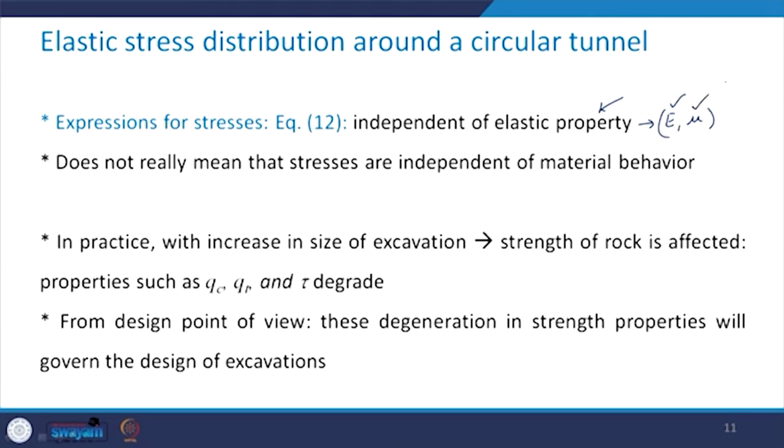So, this does not really mean that stresses are independent of the material behavior. What happens in practice is that with increase in the size of the excavation, the strength of the rock is influenced, and the strength properties such as UCS, tensile strength and the shear strength degrade.